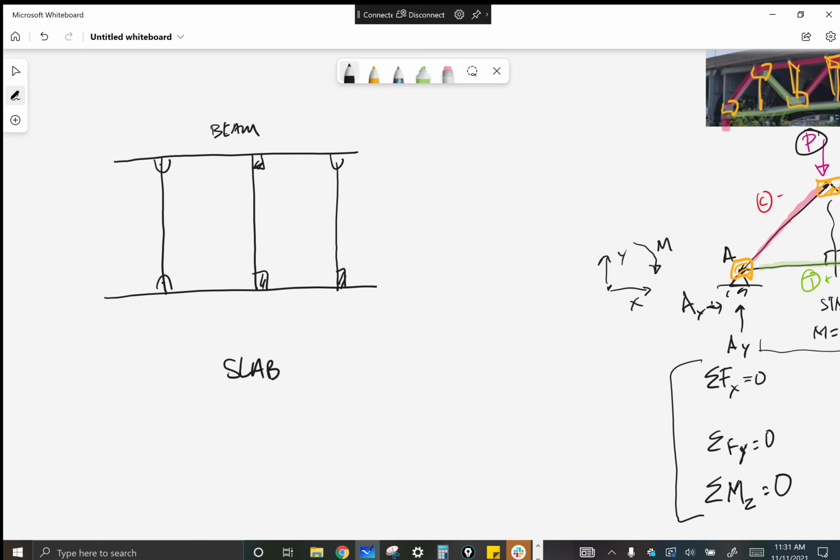And we have these different KT values for these, right? Actually, I'll put that over here. This would be something that might be on there. What's the KT for a hinged? 1. Fixed? 0.5. And for a hinged-fixed? Yeah, 0.67, let's say.